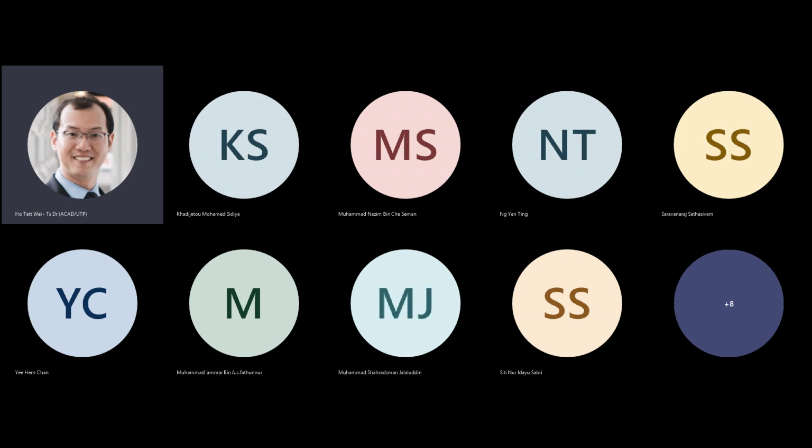And it's also dependent on the oxide, the capacitance across this. That's Cox here. And mu is a property of the material. It's the mobility of the charge carriers within the material. If you're from a semiconductor physics background, we can talk about that a little bit more. And VGS is the voltage applied to the gate here. And VTH is this kind of minimum potential difference barrier that you have to overcome in order to start pulling the charge, either the electrons or the holes, to form a conductive layer.